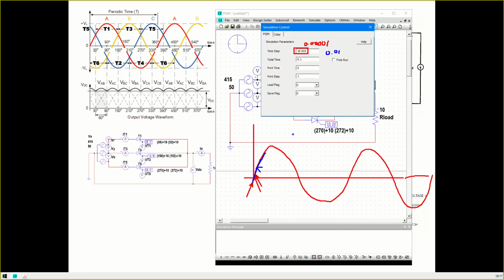This affects the number of simulation points recorded, because for the demo version, you can only have 6,000 points recorded. Therefore, when you simulate, you need to make sure you record and see a nice steady state waveform displayed.